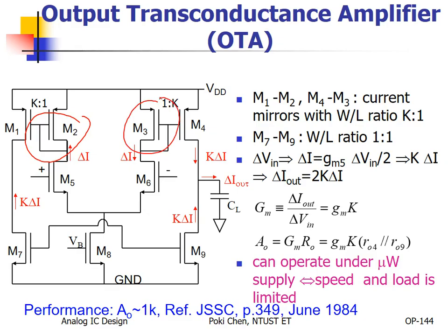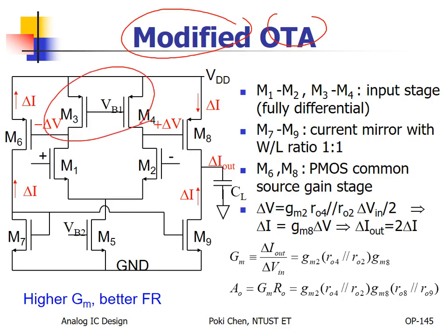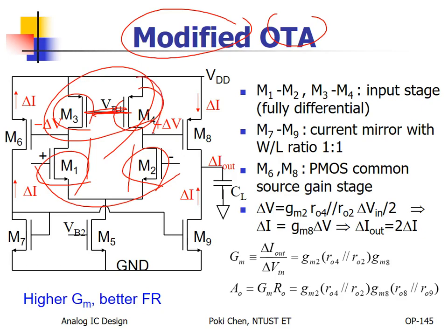From the original one, they are diode connected. It means what? They provide no voltage gain, right? Because diode connected means the gain is really small, because the output resistance is really small. Anyhow, see here, no diode connection. So again, input voltage is converted by M1, M2 into output current. But with M3, M4, DC bias, DC current, it means the resistance is much higher than before, right?